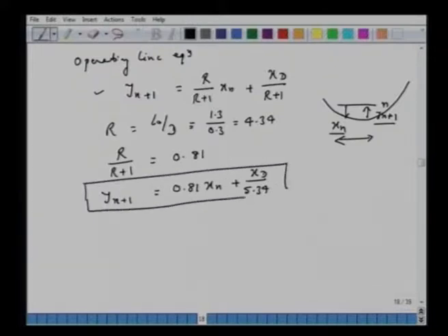Alright, so now we have equations which can give us the composition of one stream if we know the composition of the other streams here, which are 1 and 2. We have this plate 3; feed enters between 2 and 3. So this is y2 and this is x1. Since it is a total condenser, x1 is the same as y1 and the same as x0.